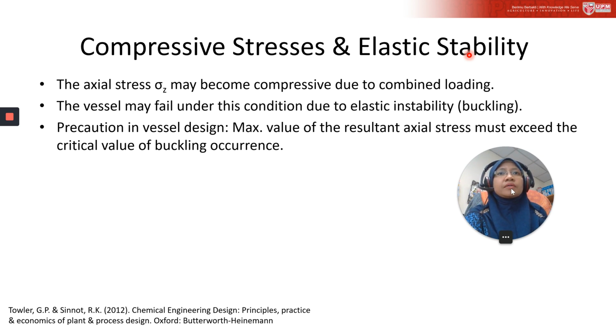When the resultant axial stress becomes compressive due to combined loading, the vessel may fail under this condition due to elastic instability, or another name for it is buckling.